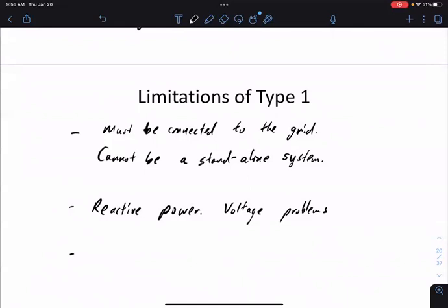Okay, so what happens when you connect, let's say, a generator, an induction machine that's not spinning, right? That's a zero frequency. When you connect that to the grid, what happens? Right, so the machine now has to catch up to the grid, very quickly catch up to the grid. But then what happens when the machine very quickly tries to catch up to the grid? Right, so your s value is very large. You have slip of 1, basically, because your frequency is 0.